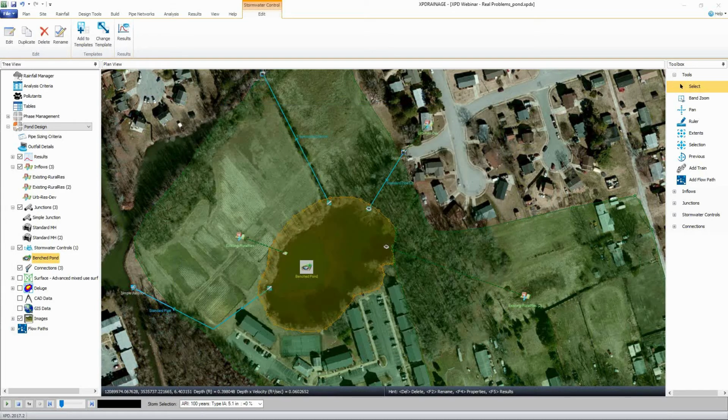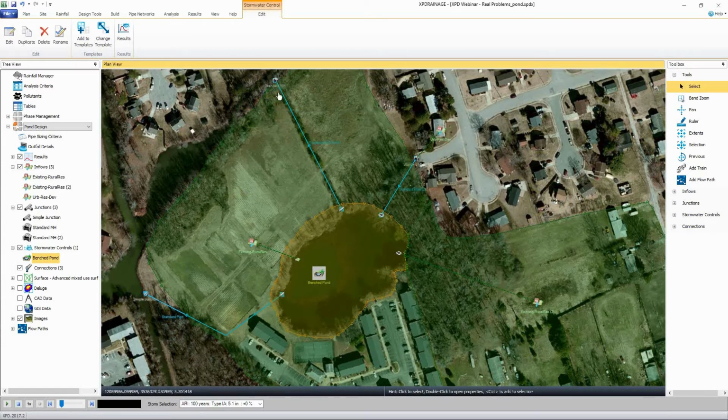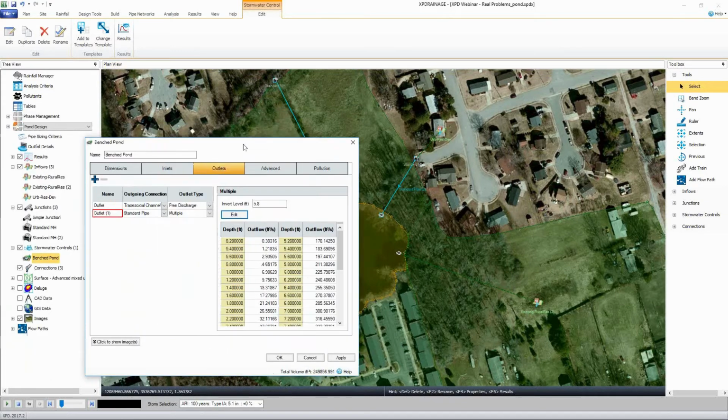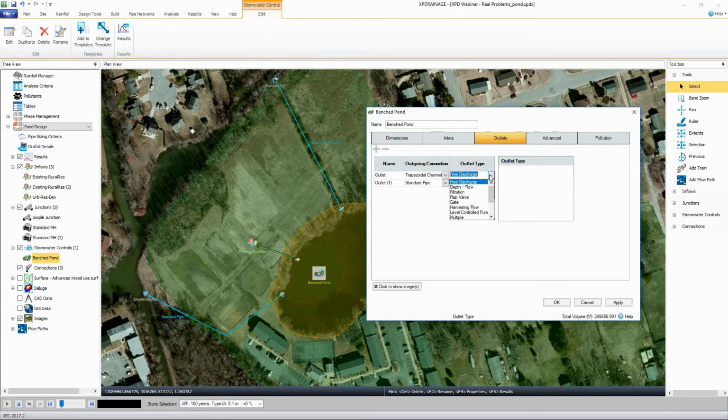For our channel, this trapezoidal channel, we can have a different kind of structure. Maybe I will set up just a basic weir. I can have a V-notch weir, just a broad crested weir. And I'll maybe say this is, again, just a 3-foot wide. In this case, might just be even just boards they put up, maybe some sort of metal barrier. And we can actually put this a few feet above the base. So I might put this at 7.8. So that's 2 feet off the base.